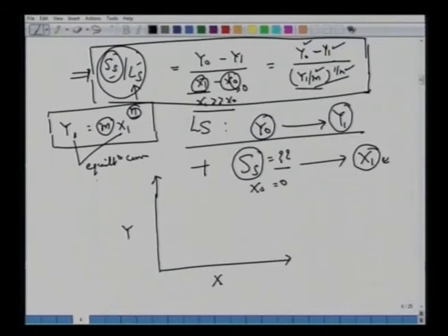Now n can assume different values. When you plot y versus x, the isotherm may be like this. If you obtain your data like this, it means n is greater than 1 and you have a very favorable isotherm, because this gives a very large capacity, a very large amount of y can be removed by this solid.